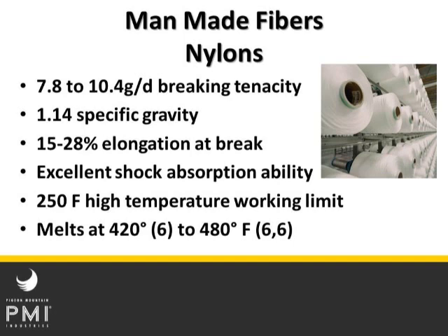Because it has this inherent elongation, it has great shock absorbing ability, and nylon has a 250 degree Fahrenheit high temperature working limit. Beyond that temperature, it's not that it fails, it just starts losing some of its properties and strength. And the closer you get to the melting point, obviously the more permanent that is, and the uglier it gets. If you happen to be hanging on a rope at 300 degrees, you probably wouldn't be happy. Hopefully none of you will ever be doing that.